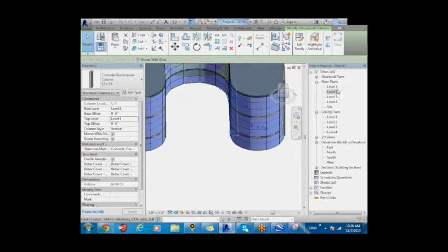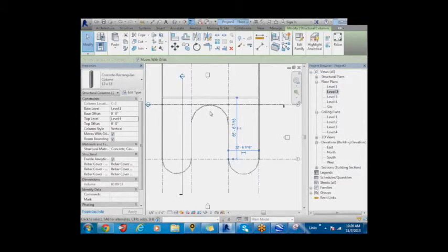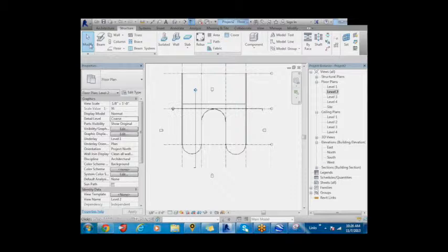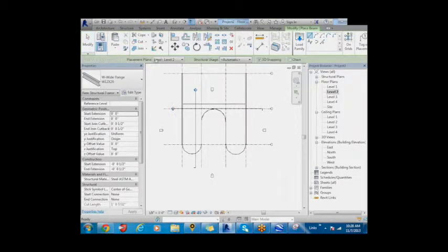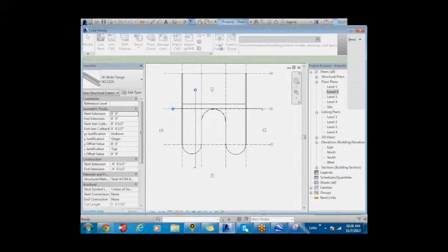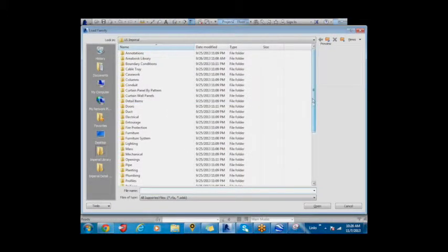So moving on from there, let's go to adding in beams. To do that, it's pretty much the same procedure. So yes, you would also need to insert concrete beams. You can find another structural framing within your family.